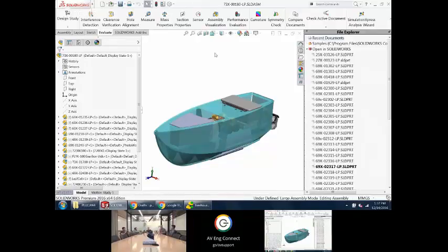Also, if you have mates that need to look at geometry, like a width mate or something like that, or a limit mate where it's comparing this part's location to this part, that's going to take longer too because it's got to evaluate where they are in space and put them where they go. Whereas something like fixing a part or mating it with just 3 coincidences to the plane or something like that, that's not going to take any time.